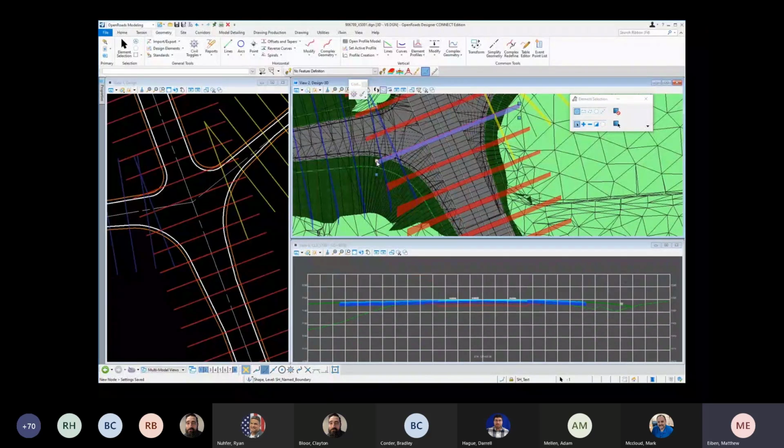So there's 4 here, and I'm on the 4th one. Then I can use the Alt key, and when I press that, it's going to preserve the angle on or off. I think if I select on this right now, that angle is locked, so it's keeping the 90-degree rectangle there. But if I tap the Alt key, you can see now that angle is no longer locked, and I can click out here.